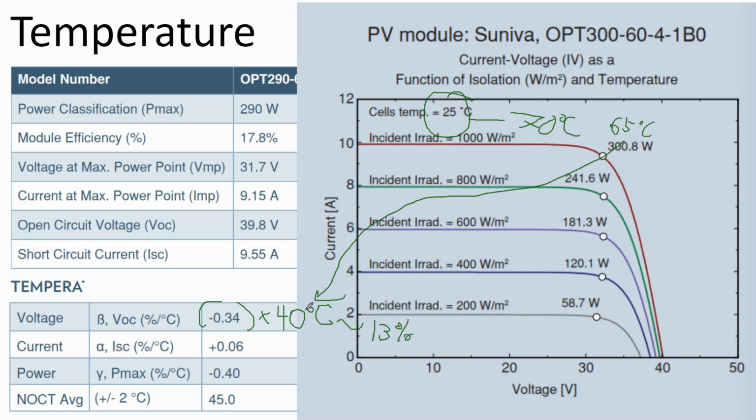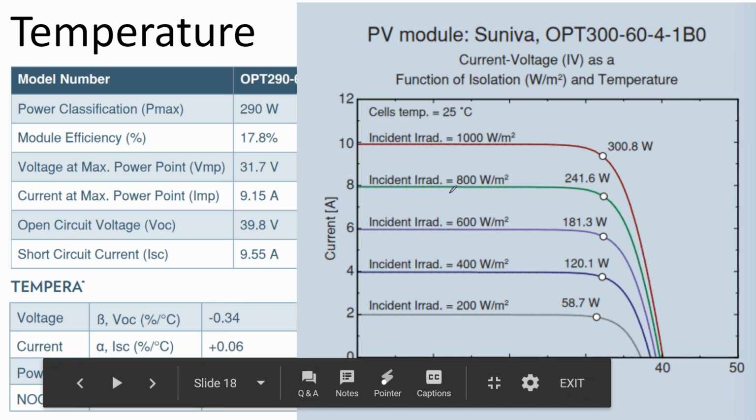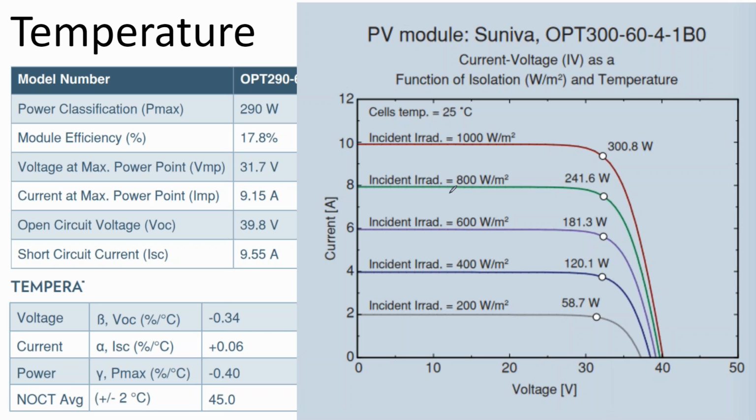alone. And so you take the wattage rating of your array, and on these hot summer days in Arizona, you already know that you're losing 13% from heat alone before other factors such as the friction of the electrons as they travel down the cable, called voltage drop. And so you can actually use all this stuff to figure out temperature loss. I just use PVwatts because it's a lot easier.